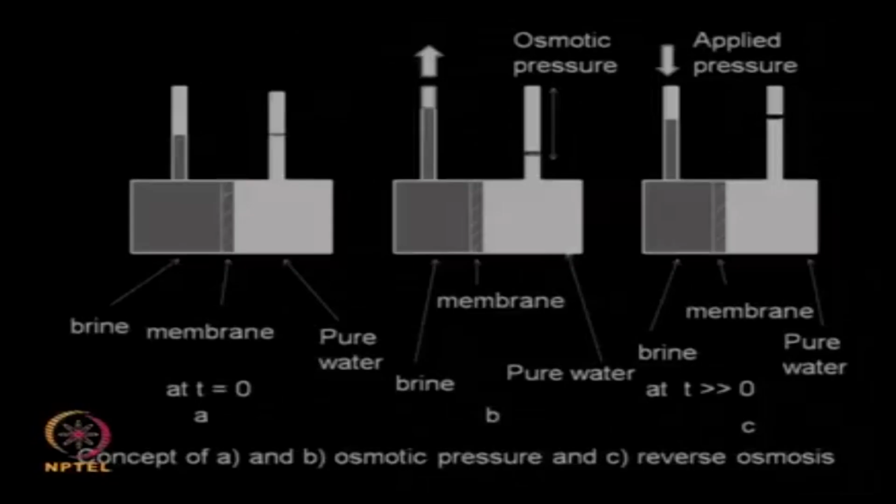You may have an ultrafiltration membrane a priori, and then finally an RO membrane, and then the water can be recycled and used for gardening and many other purposes. So that way RO has become very important nowadays, because if you are thinking about zero discharge in an industrial setup, then this is the final ultimate solution.